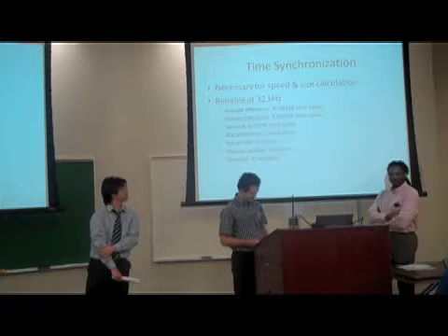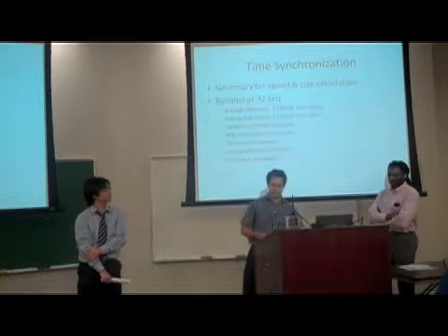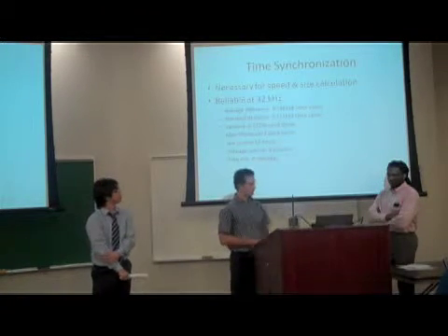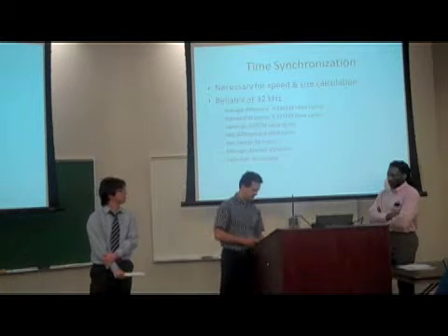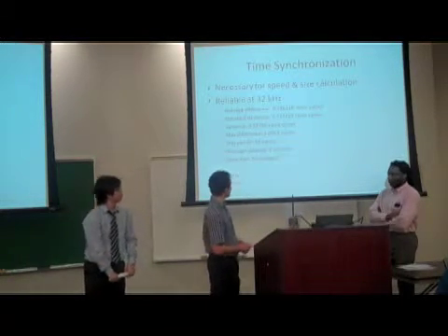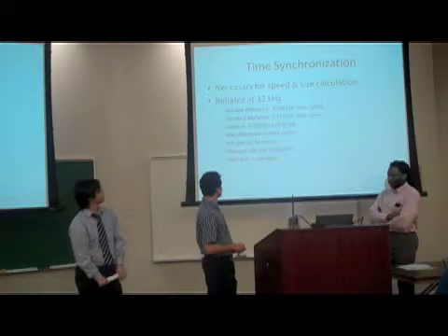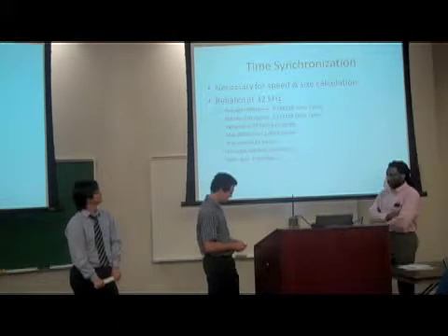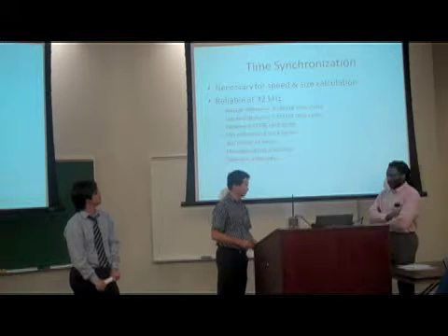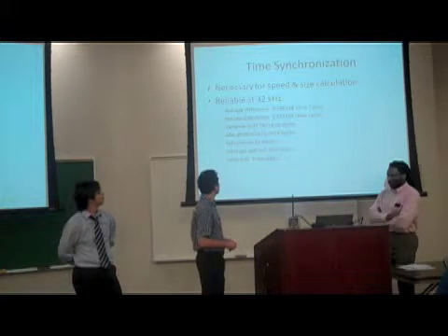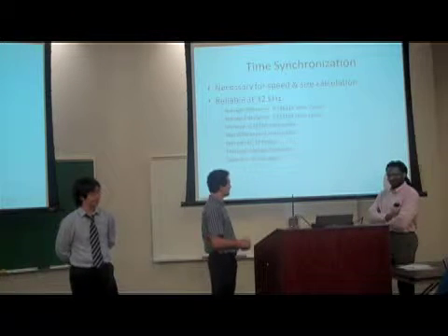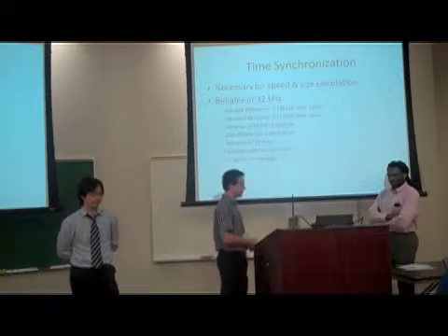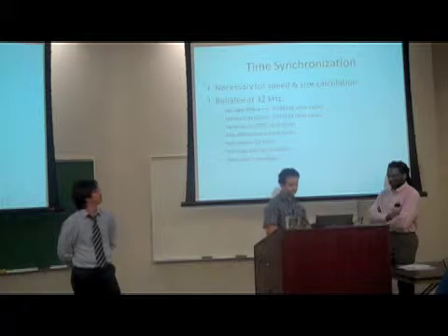So we spent a few months perfecting and testing this, and some of this information here is based off of some of the testing that we did back around Christmas. This was a test over a 12-hour period. It consisted of about 83,000 messages, and out of that we had an average difference of about 0.28 clock cycles and a standard deviation of 0.5 clock cycles.